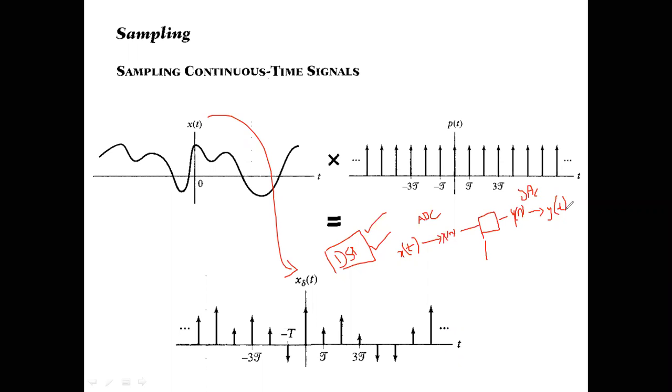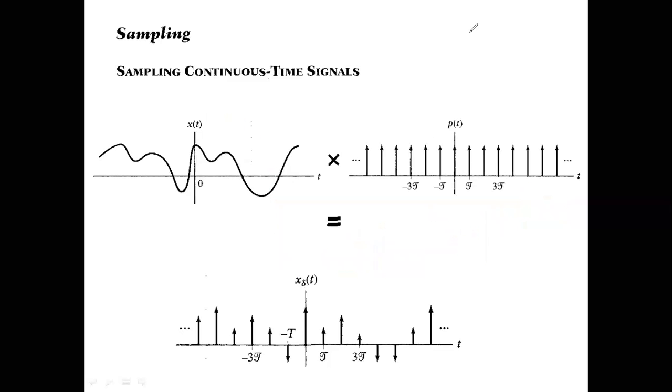But we have studied analog, we have studied digital, we have studied continuous, we have studied discrete. But how does it work, by the way? How are signals converted from continuous to discrete? That we did not study. So the sampling theorem sets the rules. How do we convert the signals from continuous to discrete?